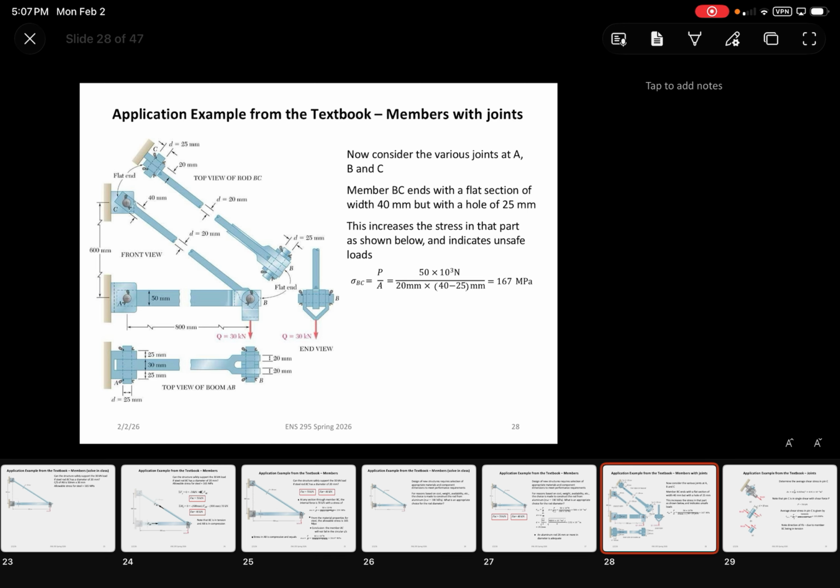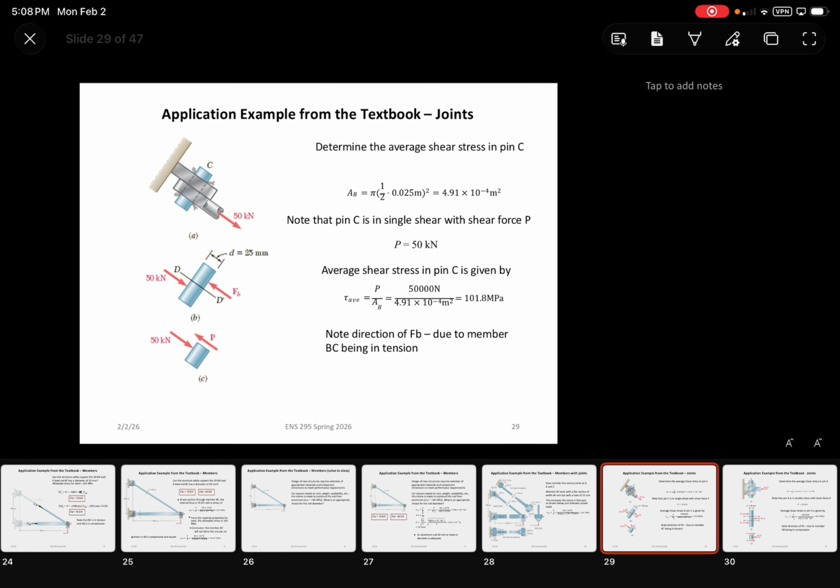But you guys can clearly see you've got pin connections located up at the top, as well as in the main frame over here. And those pins we determined were undergoing shear forces, while all of the main bars themselves were undergoing tensile and compressive forces. So it really shows you how the forces transfer between connecting components and the main members themselves. This was with the joint, just looking at the pin directly in shear.